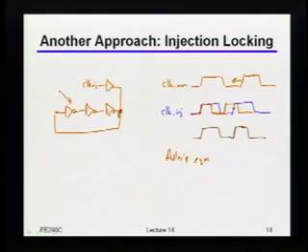Okay? So when you really do this, you might actually even want to inject it into multiple points, with different phases on those inputs. Now, alternatively, if that asymmetry is sufficiently small, or, by the way, you will typically not actually do this with a ring oscillator, but with an LC oscillator. When you have it with the LC oscillator, now you only have one stage, and so that asymmetry is not that big of a deal. I'll draw that in a little more detail later on. But you're absolutely right. If you do it exactly as I've drawn it here, that will cause some asymmetries.